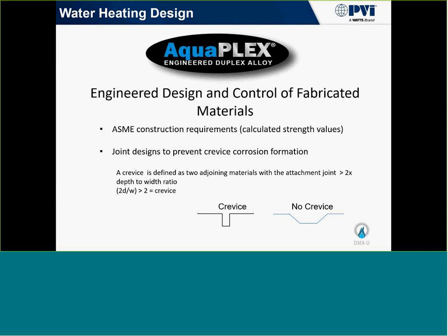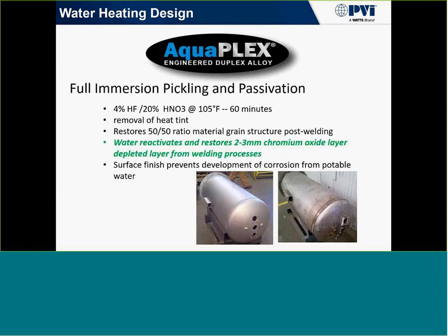With no crevice, it doesn't allow an imperfection in the tank itself where some corrosion can start. It allows the water and oxygen and everything else that we'll need in order to passivate that tank into that crevice, or into that void, which is the no crevice picture down the bottom right. When you make things with LDX2101 or Aquaplex, the bottom right-hand picture shows what it looks like after you cut it, weld it, and put that tank together.